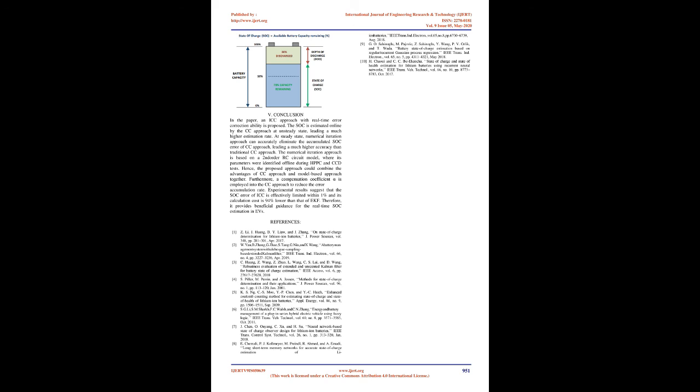The accuracy of the SOH evaluation can be improved when the battery is frequently fully charged and discharged. Finally, with simple calculation and the uncomplicated hardware requirements, the enhanced Coulomb counting algorithm can be easily implemented in all portable devices, as well as electric vehicles. In addition, the estimation error can be reduced to 1% at the operating cycle next to the re-evaluation of the SOH.